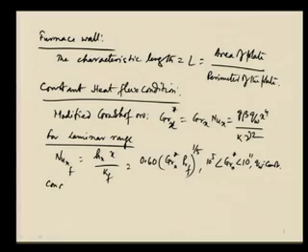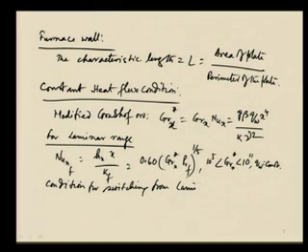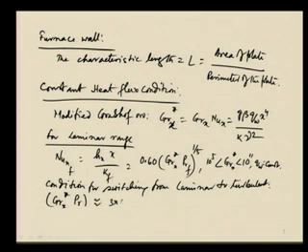The range is said to be Gr_x star into Prandtl number in the range of 3 into 10 to the power 12 to 4 into 10 to the power 13. So the range of modified Grashof number into Prandtl number is higher than 10 to the power 11, and therefore this is no longer the laminar region.